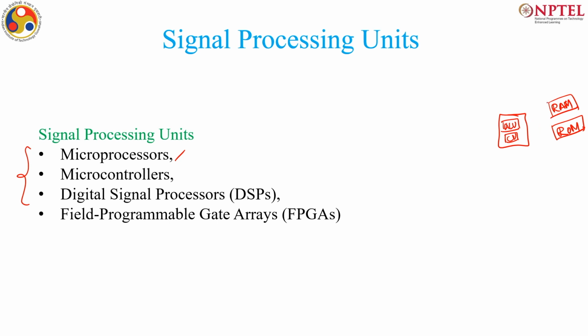The good thing is that you can easily change your RAM size depending on the application, but the bad part is that your physical size will be more. But in microcontrollers, everything is in the same IC. So, this is a microprocessor. And in DSPs there are some specialized hardware like barrel shifters and MAC hardware, which are very dedicated for signal processing tasks.